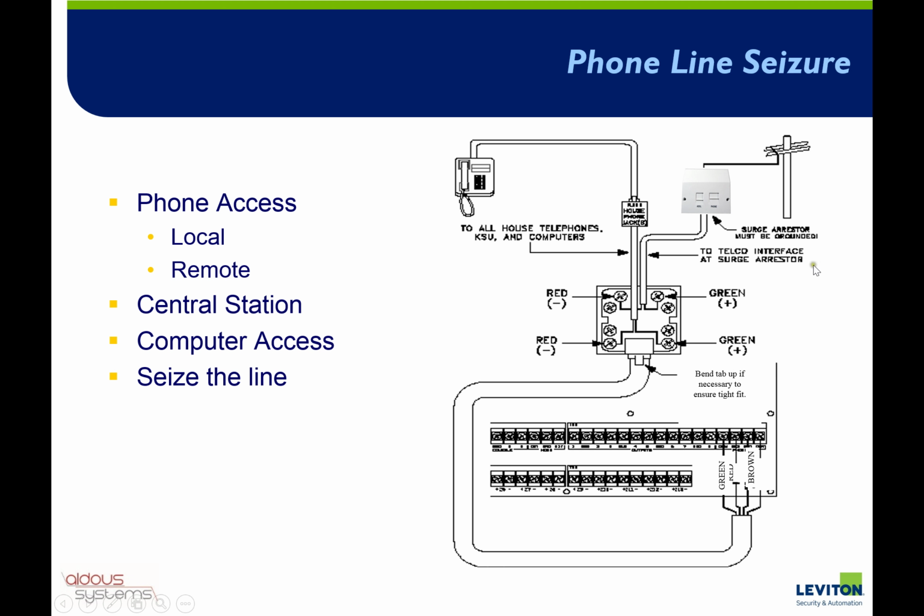For the phone connection, I mentioned in the first video, you do get this junction box, comes with the Omni. And there's also an RJ45 with a cable that has some spade connectors, and it's all color coded and it's labeled on the printed circuit board for the colors, so it's impossible to get wrong. That connects the main board to the junction box, and then you can see here's your BT master coming in from the road. Your telephone connection connects to these 2 terminals. The 2 wires connect to there and there on the red and green, the minus and plus. And then the phones for the rest of the house connect on the bottom terminals, these bottom red and green here.